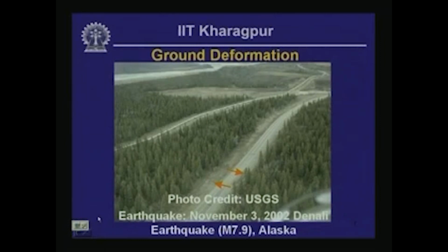In spite of the measures of placing the pipeline on roller supports, this pipeline was damaged slightly by this fault movement. Okay. Now the fault movement took place like this. This was the sense of motion, and as I mentioned, the roller supports are in that area of the pipeline to account for this type of fault movement. That largely mitigated the problem, but still there were some minor damages to the pipeline.